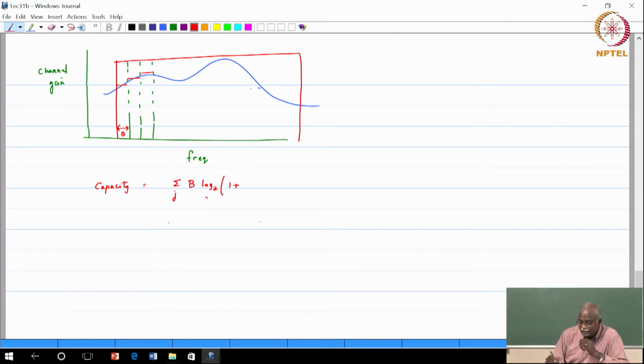Gain? What is the channel gain that you see, or what is the SNR that you will see, the gamma, which is Ps by Pn, and whatever is your channel gain, magnitude of H of j omega, continuous time frequency, magnitude squared, that is the gain that you are seeing. I am just going to write it as magnitude H of j squared times gamma.